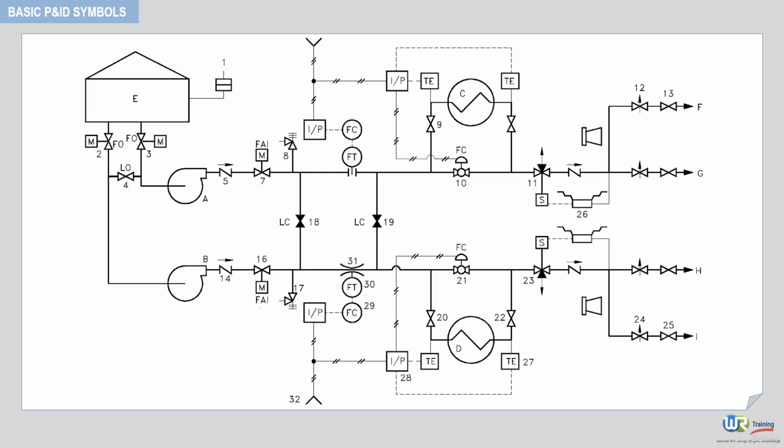This is our simplified P&ID. I use the term simplified because only equipment and line symbols are visible on this P&ID. All the P&ID concepts that we will see further ahead in this course, such as piping codes, process control and safety systems, are not depicted here. Just to keep things simple and practice only on what we have covered so far, essentially equipment symbols, flow path, and then valve position and failure modes, which will be covered in the next practice session.